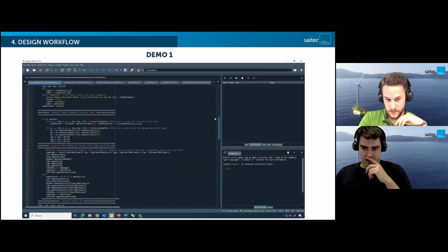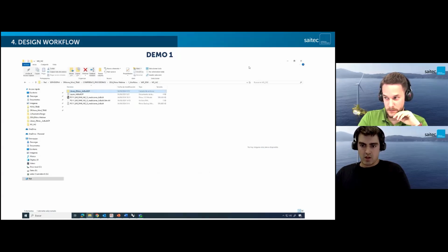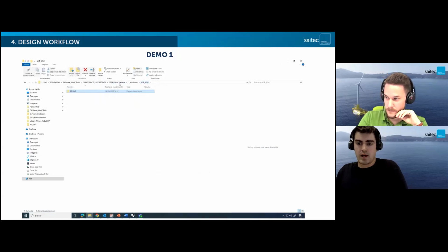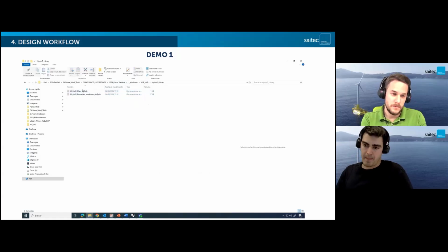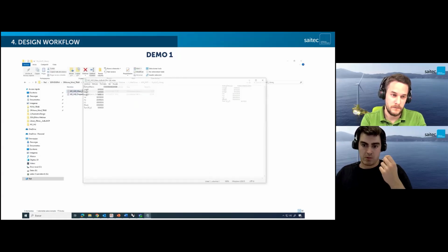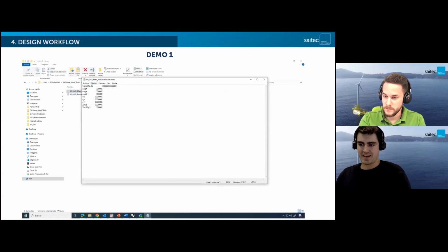And here, well, this is a list of the different iterations and the case where we define the hull height. So if now we go to the folder where we save the inputs for the hydrodynamic department, we find 3 folders. So in the hydro library, we save 2 things. We save the mass model and the breakdown. As I said, the mass model contains a total mass, center of gravity, and radius of gyration. So again, with the X.